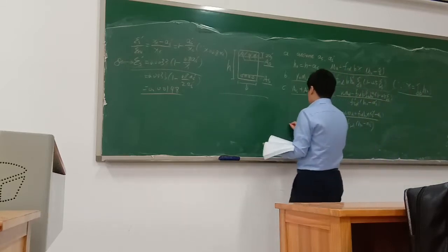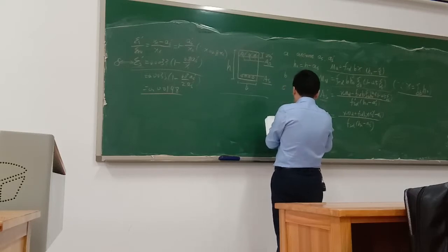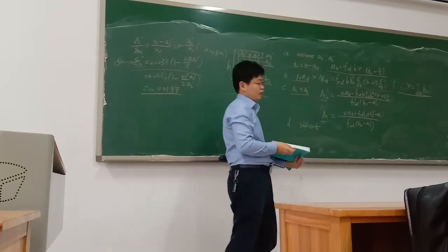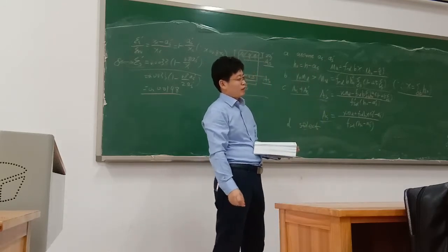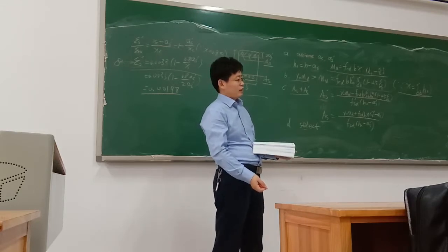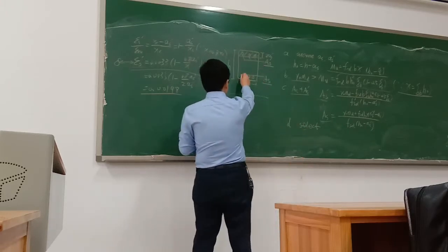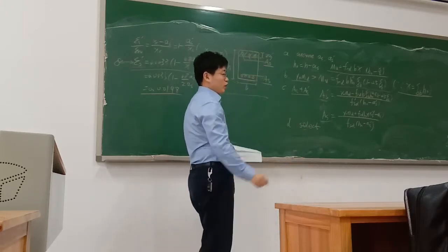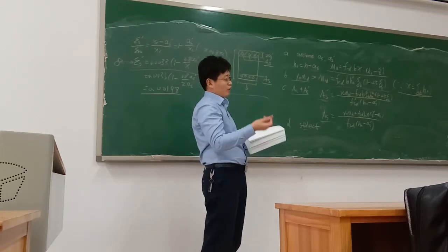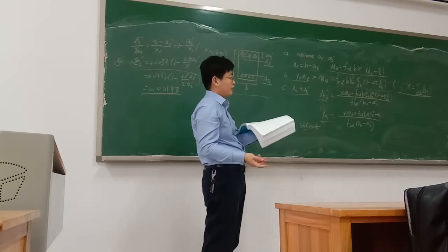So that's step E: select the diameter and the number of steel bars. Then, once you have determined which type of steel, you draw the arrangement, so one layer or two layers. After this, we go to the next step, check.